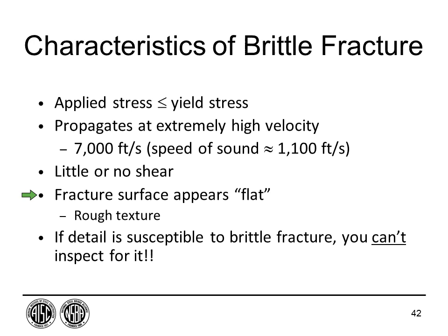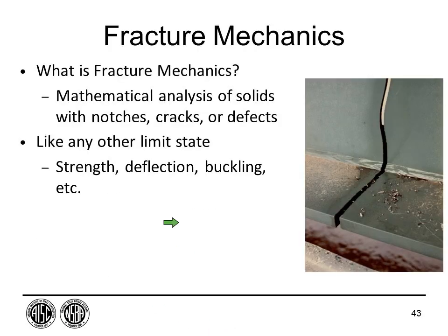But the texture is quite rough. And this is a major one to take away. If the detail is susceptible to fracture, if it's put together in a way that it would potentially just break, you cannot perform in-service inspections because it could break suddenly 5 seconds after you leave. You either accept the risk it could happen, or you do something ahead of time to prevent that from ever happening.